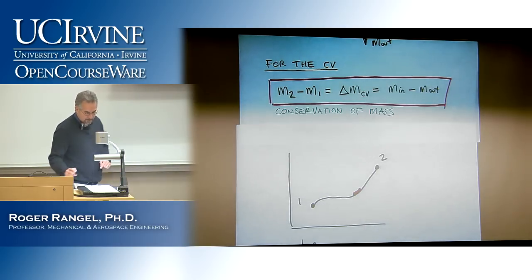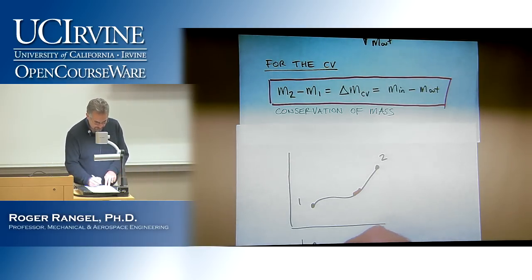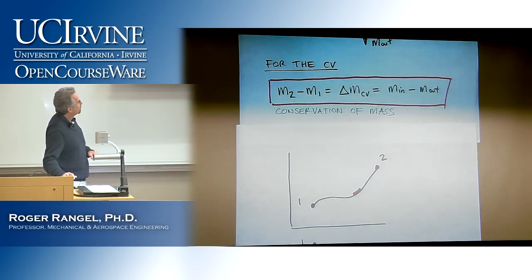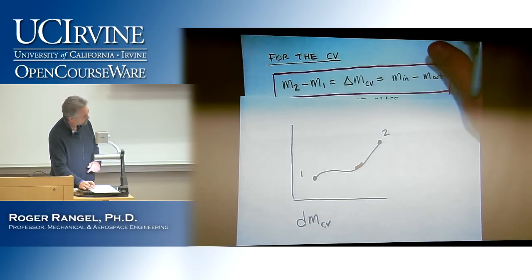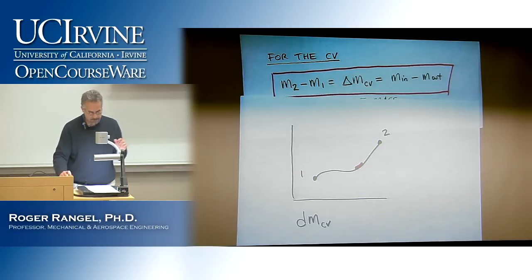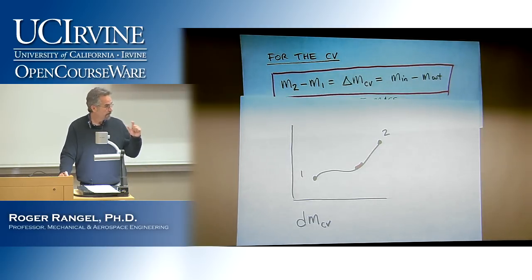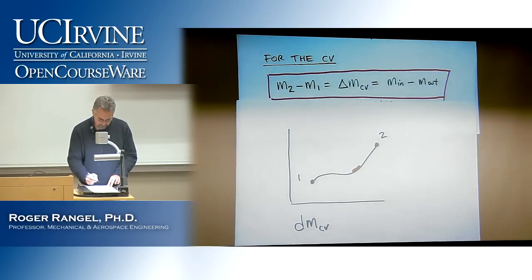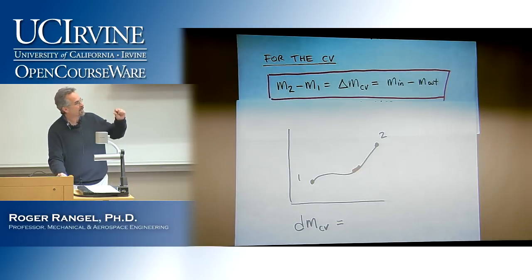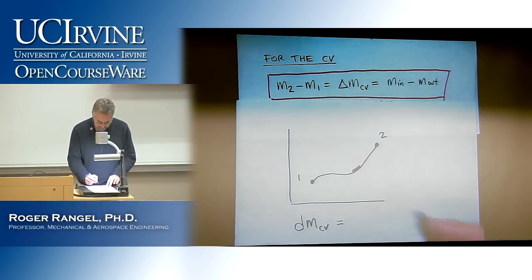That would be, and let's be specific by saying, in the control volume. So I'm looking at the same control volume, but now I am just looking at the variation over an infinitesimal amount of time. And of course, applying the same calculations here, now I would have, of course, only an infinitesimal amount of mass coming in.